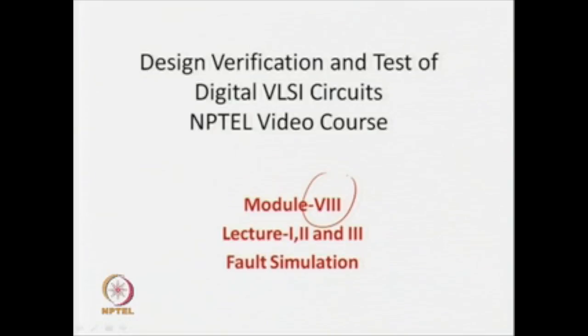In this module, what we are going to see is how you can generate the test patterns. Given a circuit with n number of faults, after fault collapsing by dominance and equivalence you can reduce the number of faults. Then, for the final list of faults, how can you generate test patterns which can detect the faults? That is called test pattern generation. So in module number 8, our main emphasis will be how to find patterns which can detect the stuck-at faults in your circuit.